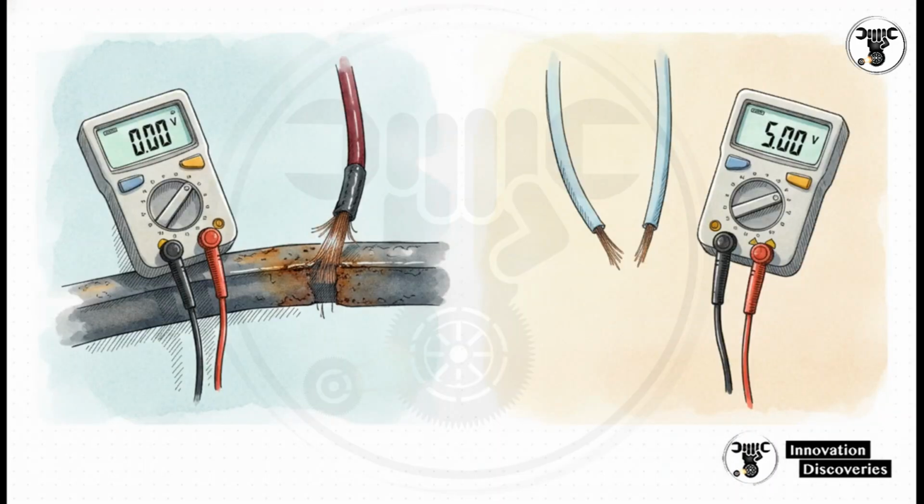This brilliantly illustrates how we use our code knowledge to actually guide our electrical testing. Let's compare P0452 and P0453. A P0452 is a low input code. This usually means the sensor signal is stuck at 0 volts, which strongly indicates an electrical short to ground somewhere in the wiring harness. On the flip side, a P0453 is a high input code, meaning the signal is stuck at 5 volts, which points to an open circuit or a broken wire. These codes are telling you exactly what kind of electrical fault to go looking for.